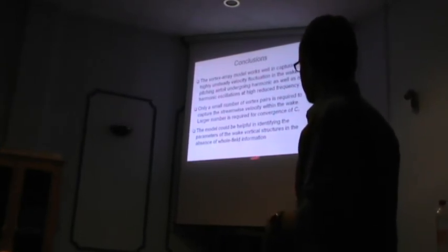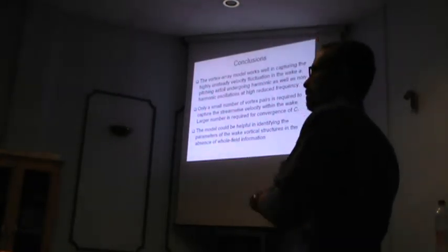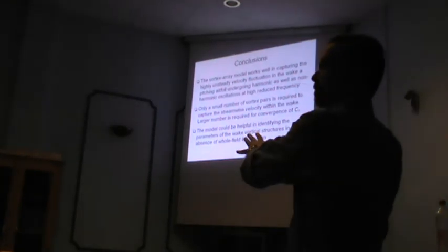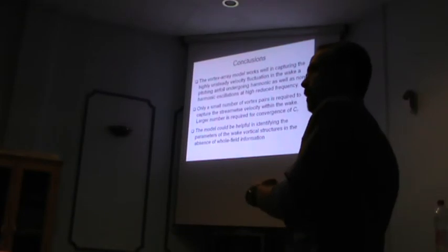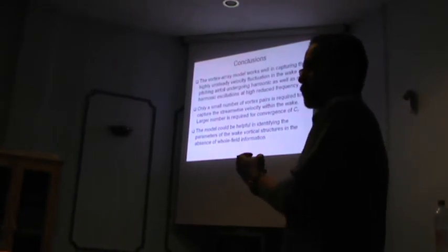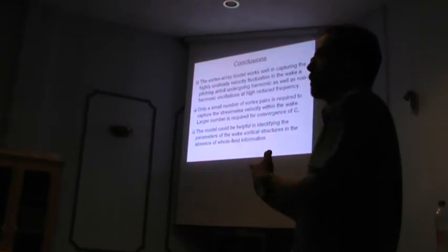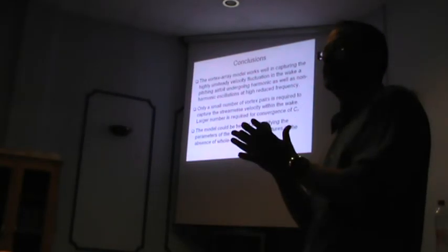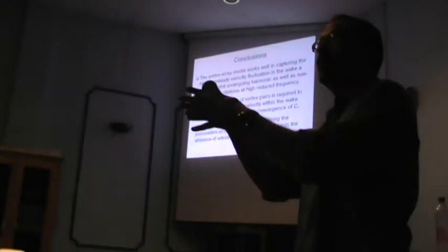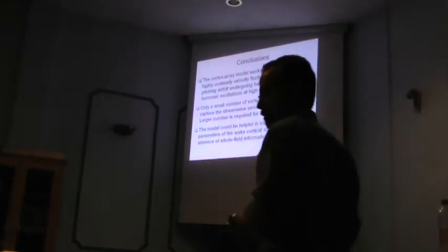But in addition, for an experimentalist, if you have only single velocity measurements and a periodic flow that is dominated by vortex structures, potentially some turbomachine that still has a well-organized vortex structure behind it, then you can use a model like this to extract information beyond what you're measuring. Whatever limited set of data you have, you can use it to make sure that the model is working well. Once you have that confidence, you can use the model to get additional information.